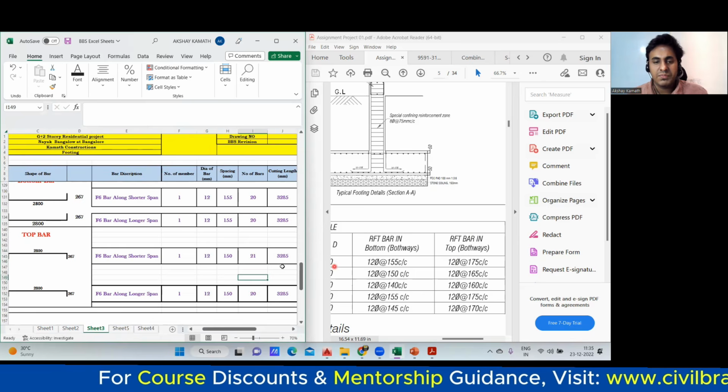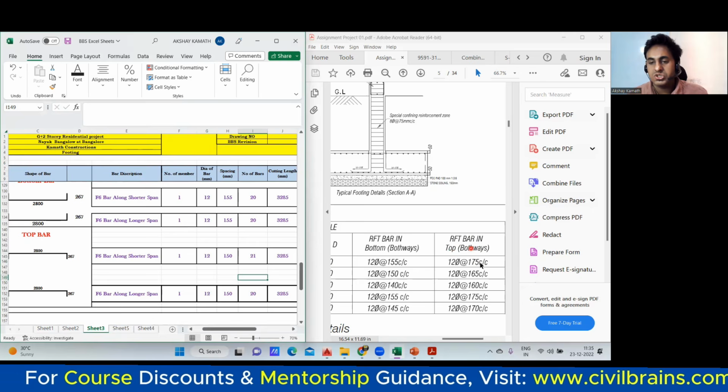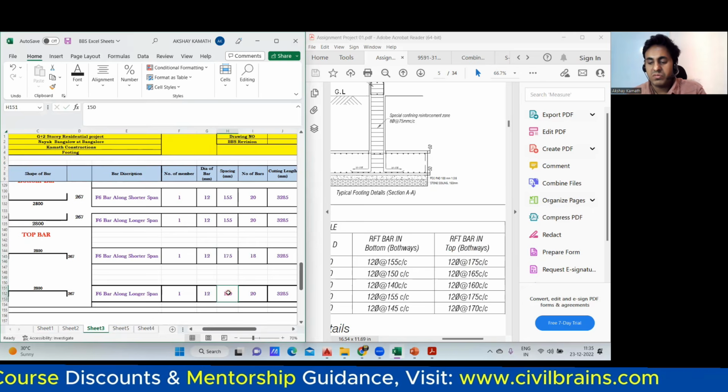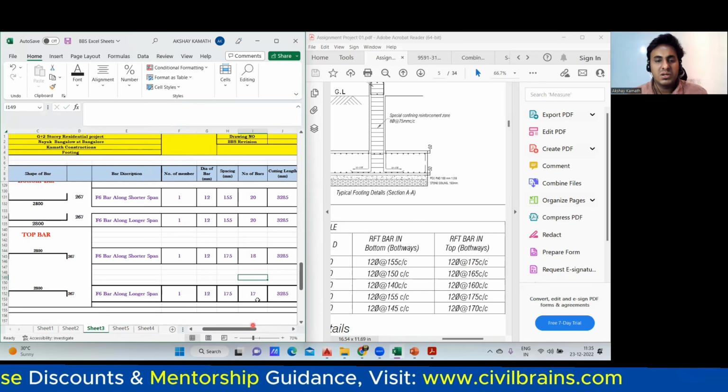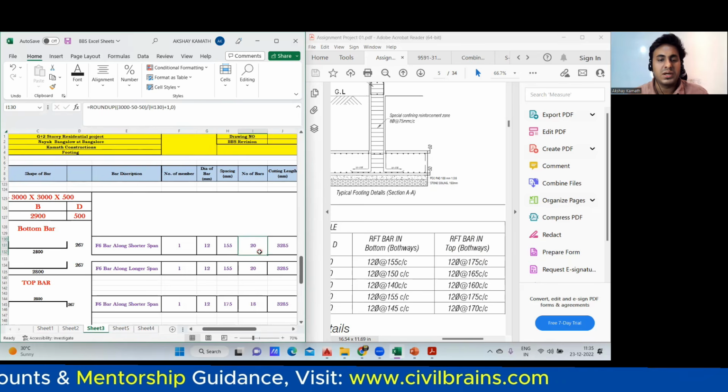Okay. 12, 12. And what is the spacing in the top reinforcement? See, it's top written in both ways, shorter and longer. It is 175. So I'm making 175 here. I'm making 175 here. Finish. Done. Okay. Accordingly, you don't have to do anything. You got the answer. Total 20 bar is required.